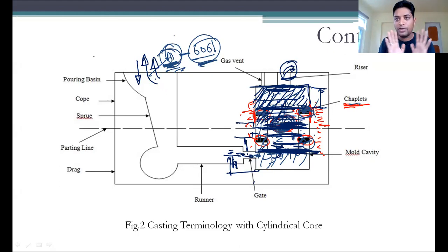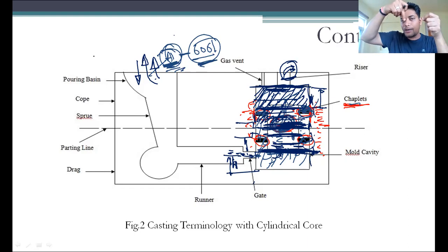Or what we can do is, by the way we are not doing this one, but still there is a possibility, we can add heating elements. Different types of heating elements are there. They will maintain a constant temperature of like 300, 400, 500 degrees centigrade. We can attach them over here along with this molding sand. Whatever the material at the boundaries, because from the boundaries only this material tries to become solid or semi-solid, we keep this heating element at the boundaries, so this material does not easily become solidified till it fills up to the specific height that we are keeping.